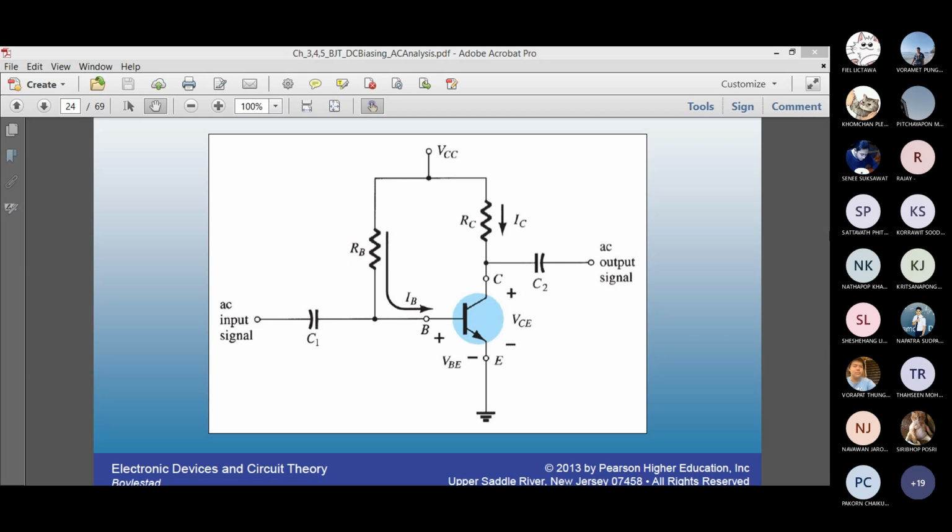We should ignore it. When you ignore it, is it an open circuit or a closed circuit? Open circuit. It's an open circuit. The current through the capacitor, IC, equals C dV over dt, but in the case of DC voltage, V is not changing with time, so it's a constant, and the derivative of a constant is 0. No current means it's an open circuit. For any DC analysis, we should definitely ignore the capacitor and ignore the AC signal. You just concern yourself with the DC.